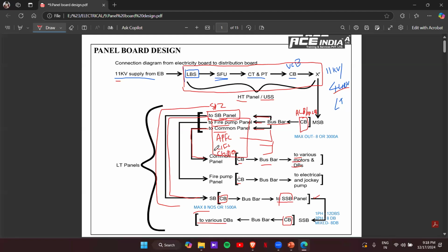And these connections should be given full backup condition, whatever the condition is. Okay, so if there is no power supply, this panel should be working as in the normal condition. Okay. A chiller we can exclude depending upon the condition. If it is a commercial base like a shopping mall or hospital, those should be given full backup as well. Okay.